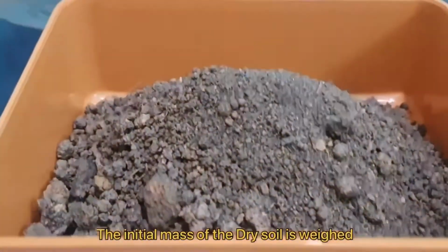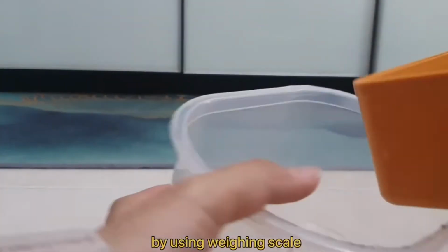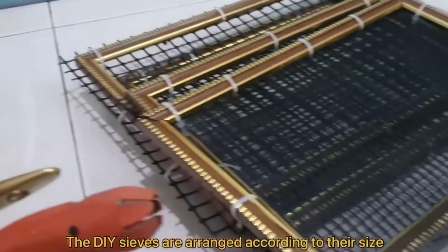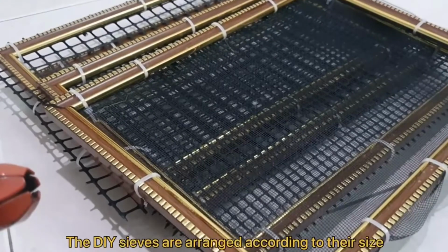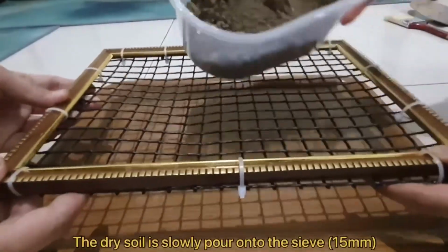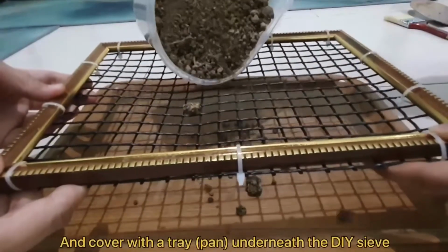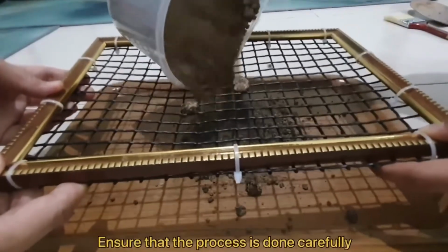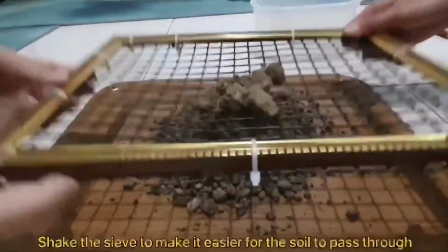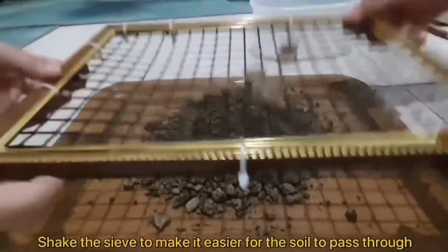The initial mass of the dry soil is weighed by using the weighing scale and the weight is recorded. Transfer the soil into an empty container. The DIY sieves are arranged according to their size from largest to smallest. The dry soil is slowly poured on the sieve and covered with a tray underneath the DIY sieve. Ensure that the process is done carefully to avoid spillage of the soil sample. Shake the sieve to make it easier for the soil to pass through.